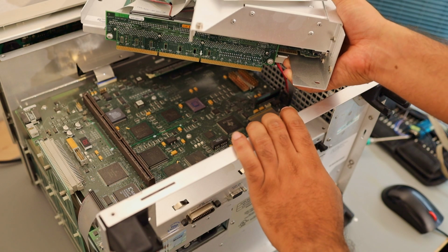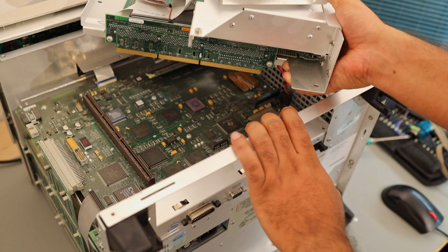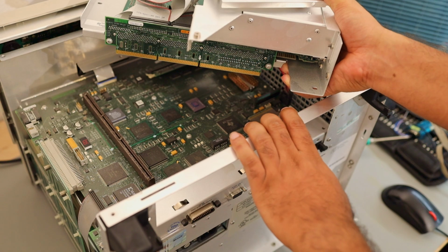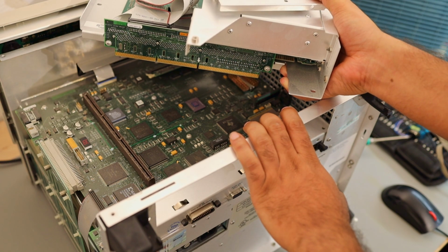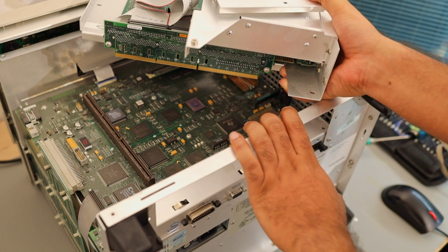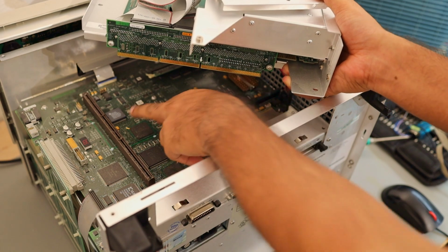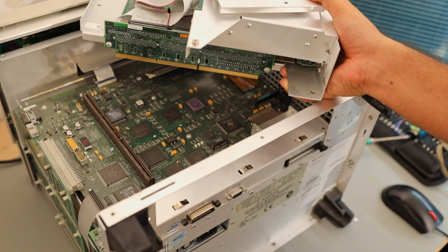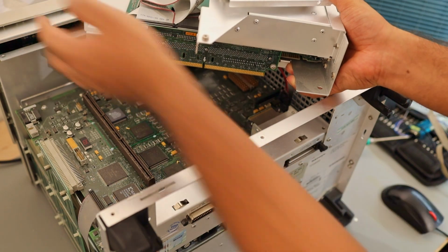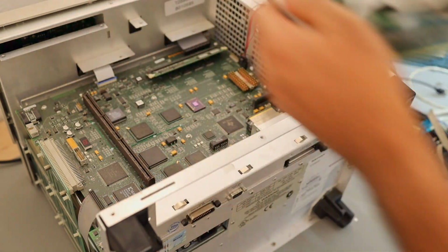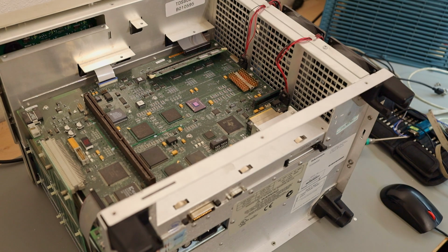We will also check the power consumption of that particular NVRAM chip. I hope that is not consuming too much power. Otherwise we need to replace it and find an alternative for that. There are multiple alternatives available. You can buy the whole NVRAM module from Maxim or Mouser, or you can also get FRAM modules available nowadays for this. So let's put this motherboard aside and we will focus just on the VxWorks board.